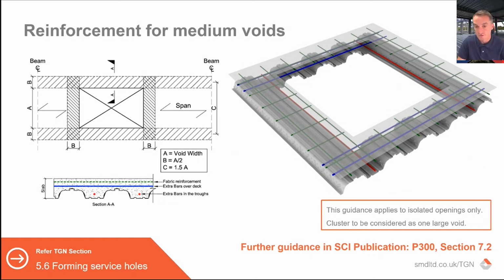But clearly you need to know where that void is and design the reinforcement before pouring, and often voids are a late client requirement. So a late client requirement for a large void is going to need supports below, so beam supports underneath the deck.